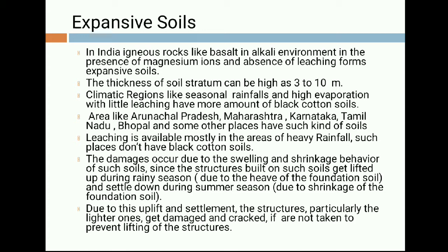Due to this uplift and settlement, the structures, particularly the lighter ones, get damaged and cracked if measures are not taken to prevent lifting of the structures. That is, if proper care is not taken, there is total possibility that the structure might experience uplift because of swelling characteristic and settlement because of shrinking property of the black cotton soil.